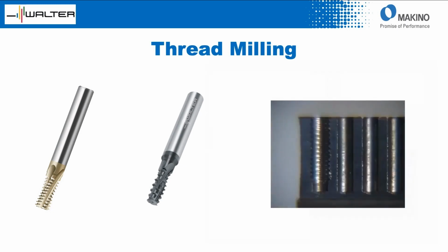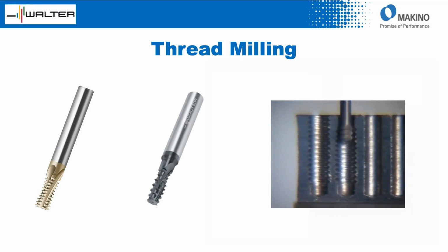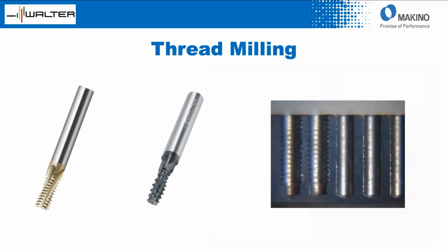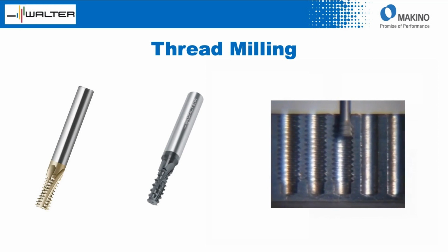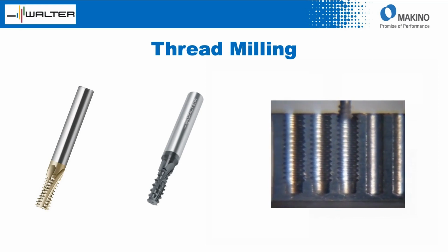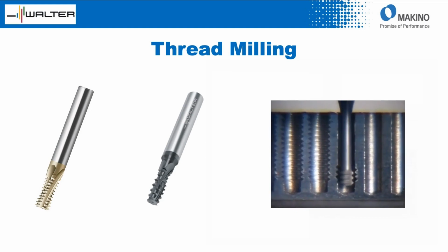Lastly, we have the orbital thread mills. This is a very great design, especially for small holes and deep lengths. Yeah, just from a reference standpoint, that's a 4 millimeter hole, pretty long L to D too, and you can see it's very effective at creating those threads. Yeah, I think that's 3.5 or 4 times D, and it's actually pretty quick. We're slowing it down on this one so you can see what it's doing.